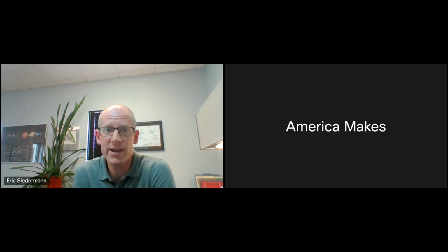That's the ISO DTR 52905. That one's being led by Ben Dutton from the Manufacturing Technology Center in the UK. That is also a guide for NDE methods for additive manufacturing. That has a PCRT section. And then there's a standard practice in development through ASTM, the F42 Committee for Additive Manufacturing, that's led by Steve James. And that standard is establishing acceptability criteria for aerospace additive manufacturing components, and it highlights the NDE methods and accompanying standard practices that can be applied to inspect those components, and PCRT is among the methods included in that standard.